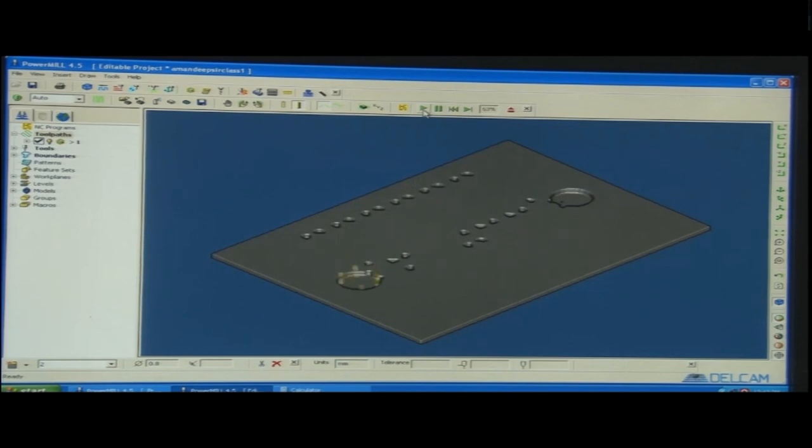So, now the complete simulation, I just press the play button. With this command system, we can get the complete code of the whole job. It is just the plunging. Where does the plunging happen? When we fix the fixed coordinates, you can see this pattern that is built here on the workpiece. In this pattern, at each corner, whenever the tool turns, the plunge happens. The tool comes down or comes out. So, that is being shown in this simulation.